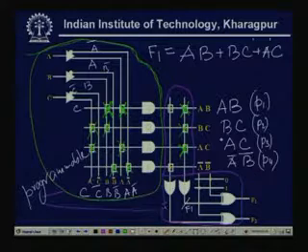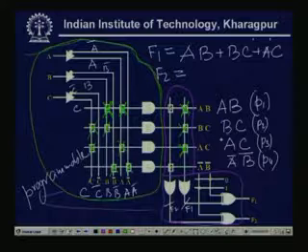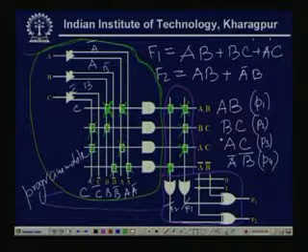And if I assume my F2 is here, then my F2 is the sum of two min product terms, P1 and P4. So, P1 plus P4, and P1 plus P4 is AB plus A bar B bar. So, these are the two functions F1 and F2.